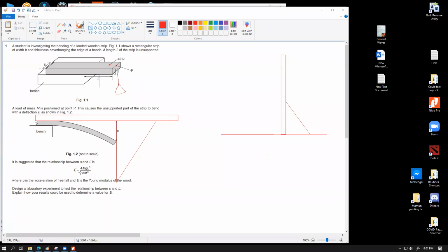Because you cannot do this experiment where the plank goes beyond the elastic limit or the limit of proportionality. You can see over here this equation is a perfectly linear equation, y equals mx, or that sort of an equation, so we do not want that to happen. So this is a type of precaution that we can talk about.